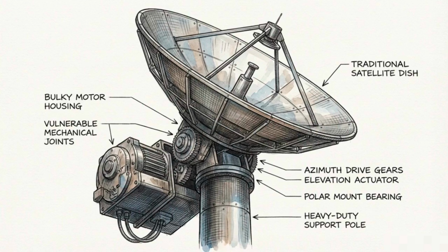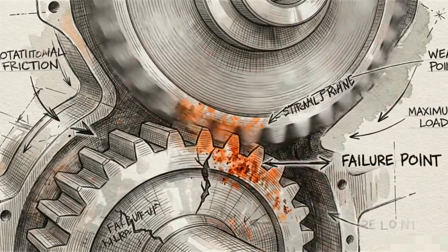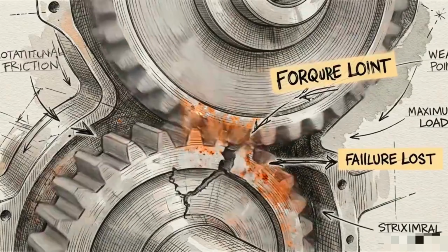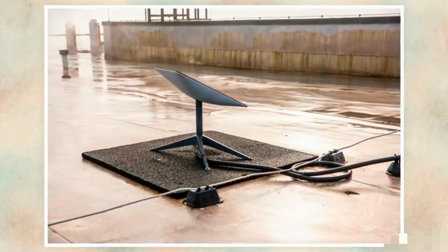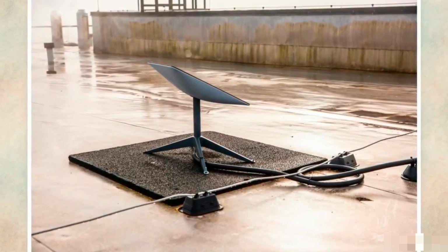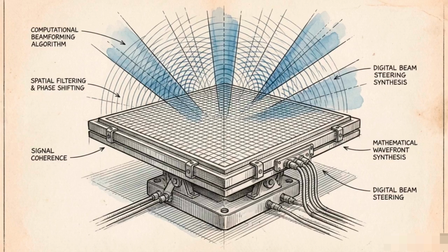Traditional satellite dishes use physical motors to point a parabolic reflector. Mechanical gears are too slow and prone to wear to continuously sweep across the sky, tracking targets at these orbital velocities. The modern hardware solution eliminates physical movement entirely, utilizing a strictly solid-state, flat-panel architecture. To solve the orbital tracking problem, engineers replaced mechanical motion with computational wave physics.